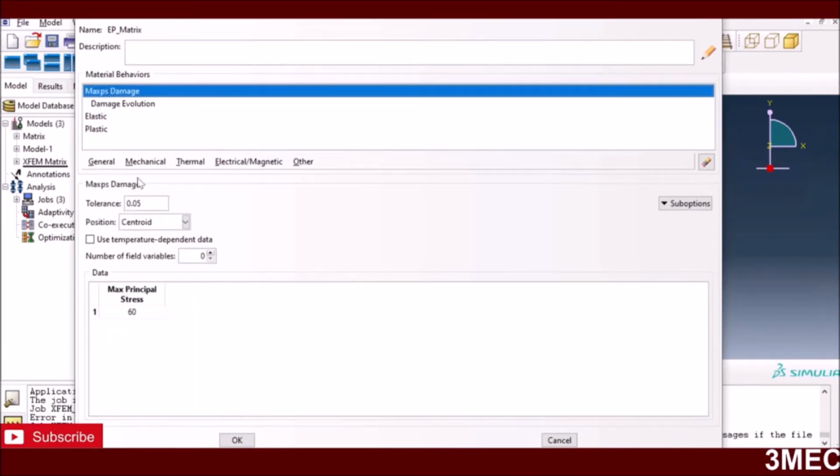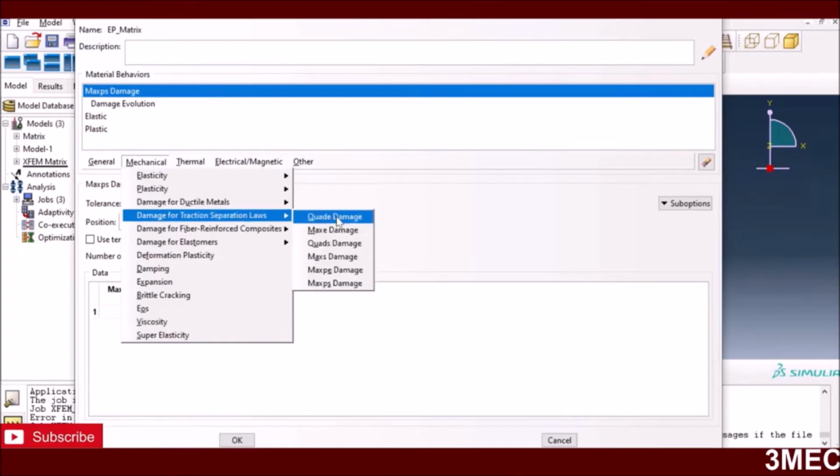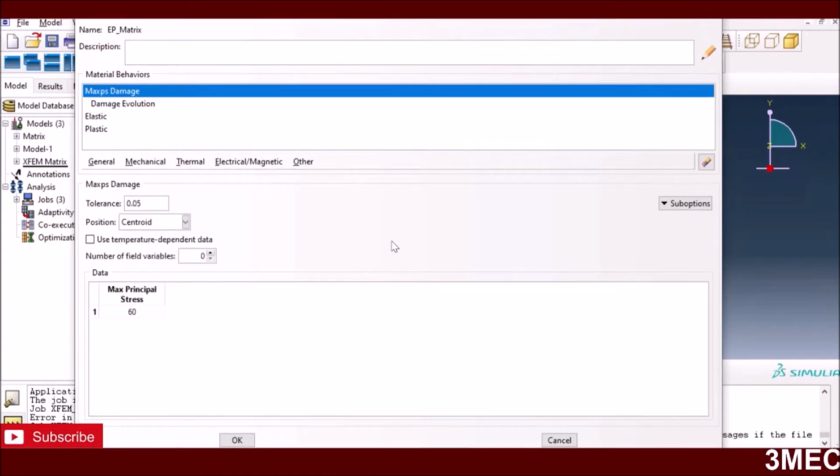For the stress criteria, I use mechanical, and then I go to damage. In this case you have many different criteria available, like these ones. You can also use traction separation based laws. So I have used this maximum principal stress damage criteria. They use a critical stress criteria using the node release technique. I didn't go for that because XFEM, in my opinion, might do a better job. Or you can use a cohesive model as well, or you can use the node release technique as they did, which was in an older version of ABAQUS, and they didn't have XFEM, or even cohesive models were very new at that time. People were only using subroutines, UEL subroutines at that time.